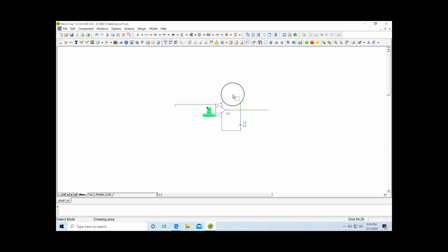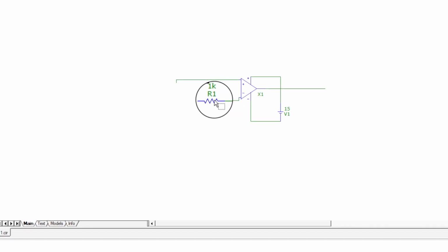See that? So I'm going to come down here and grab him and see how he stretches like a rubber band. I'm just going to pull him out so there's a place to connect another line right there, okay? Because I don't want the pins to pin with another pin on top of it. I like to have a little trace there that I can grab onto.